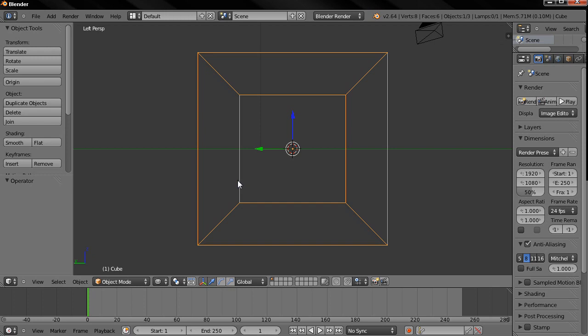A perspective view is geometrically constructed this way. You have a scene in 3D and you are an observer placed at a point O. The 2D perspective scene is built by placing a plane, a sheet of paper, where the 2D scene is to be drawn in front of point O, perpendicular to the viewing direction.